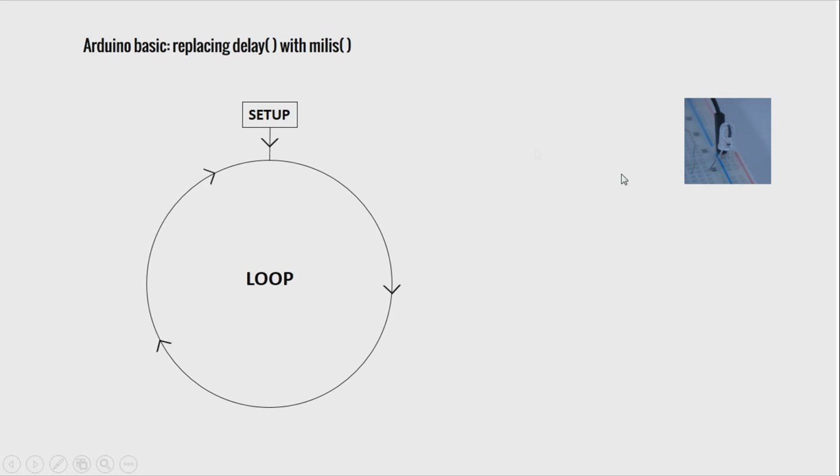We will use the blink LED again as an example. Let's say we want the LED to stay on for 500 milliseconds, and it will be off for 300 milliseconds before it turns on again. Basically, there are still 2 main actions, which are turning the LED on and turning it off. The main difference is that we do not trigger these 2 actions directly, but it will depend on the time.